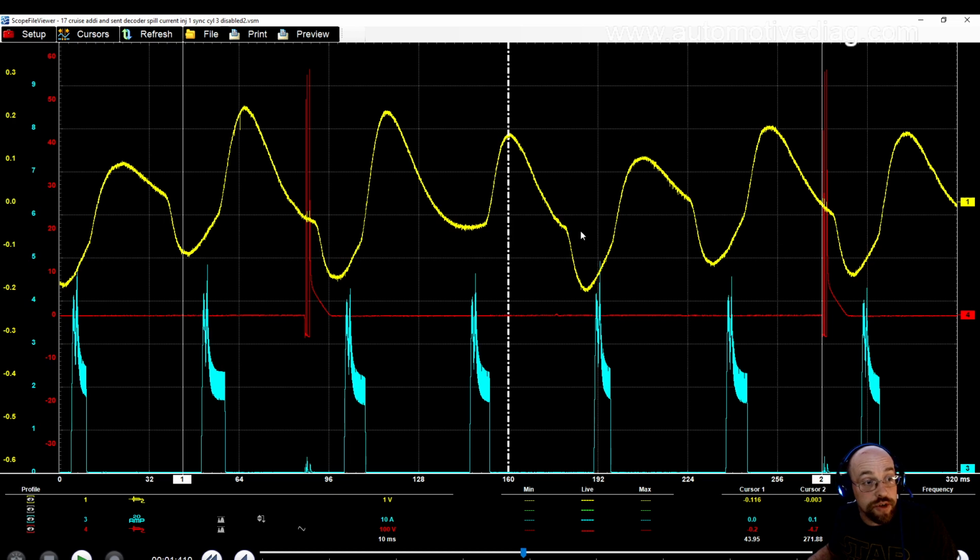And in this case, you can actually see it because no fuel injector event happened here. This is 1, here's 3, and there's literally no flow curve. That can clearly be seen. And because of that, the overall pressure is higher. So you can see the next spill event duty cycle is much shorter, and it's trying to bring the pressure down because the average pressure is too high. And then you'll see that the pressure comes down, the next pulse is not near as high, and then you can see that it starts to bring the duty cycle back in to try to stabilize it.